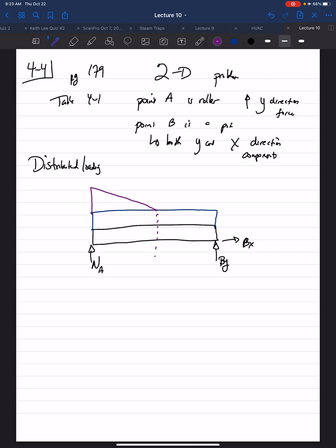So we said in our previous work that to represent the resultant force from a distributed loading is pretty much the area. Use the area formula. So for the rectangular, the load intensity is 600 Newtons per meter. And for the triangular, it is the difference of 900 Newtons per meter and the 600 Newtons per meter. So that gives the intensity here 300 Newtons per meter.